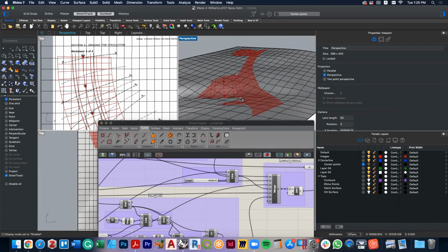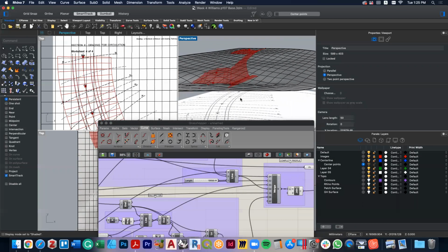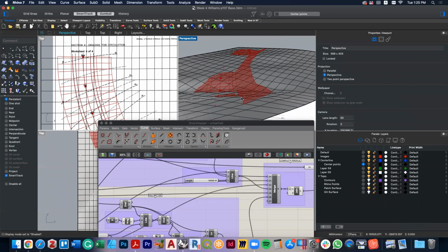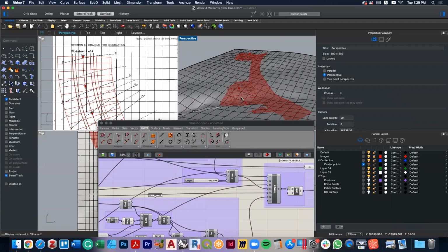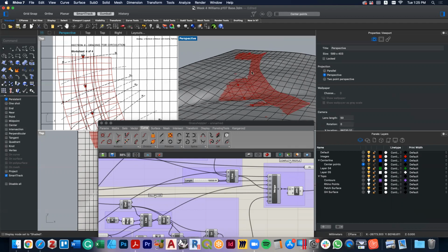When we're at this position here, there is a little bit of cut, right? There's a little bit of cut. We can see the swale disappearing in there. And so really, if we think about looking at these embankments, we can play around with how those heights are and whether or not we have to mirror fill on both sides, or cut on both sides. And then at this point, what we do afterwards is move into the process from my previous tutorial, as we did for the platform, where we start chopping, intersecting the meshes with each other to create the lines of no cut, no fill. We start subtracting from the meshes below to come up with the final landscape. So this is the sort of process we're going through.